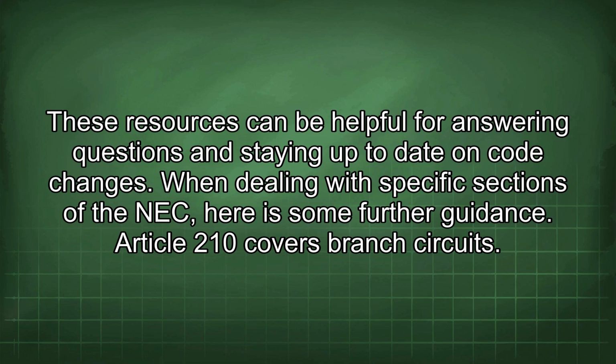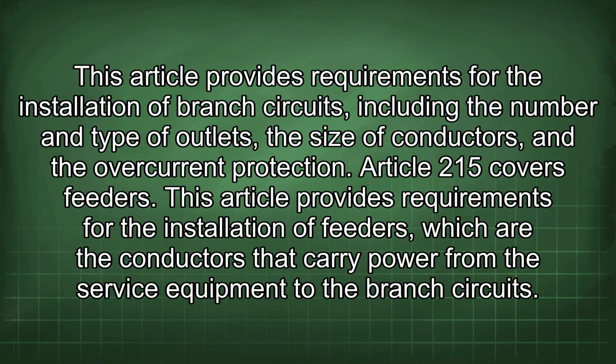Article 210 covers branch circuits. This article provides requirements for the installation of branch circuits, including the number and type of outlets, the size of conductors, and the overcurrent protection. Article 215 covers feeders. This article provides requirements for the installation of feeders, which are the conductors that carry power from the service equipment to the branch circuits.